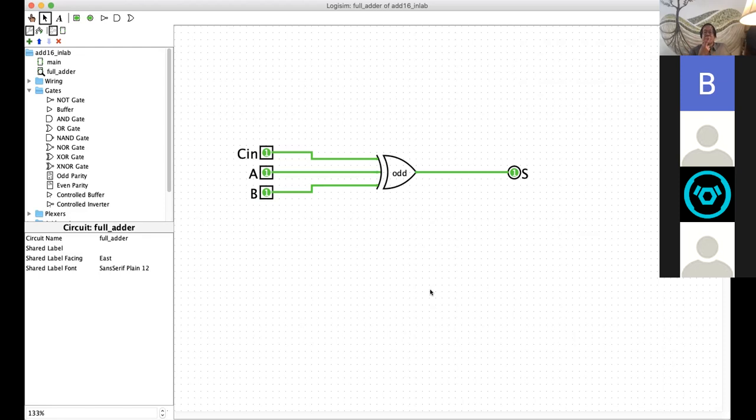Basically, it has 3 AND gates at the first level, closer to the input, where each AND gate has 2 inputs, and there are three possible combinations of the three inputs. So these three AND gates will take all possible combinations of two inputs, right? And then once you get the outputs from the AND gates, you gather them into an OR gate. And the output of the OR gate is then the carry out, right?